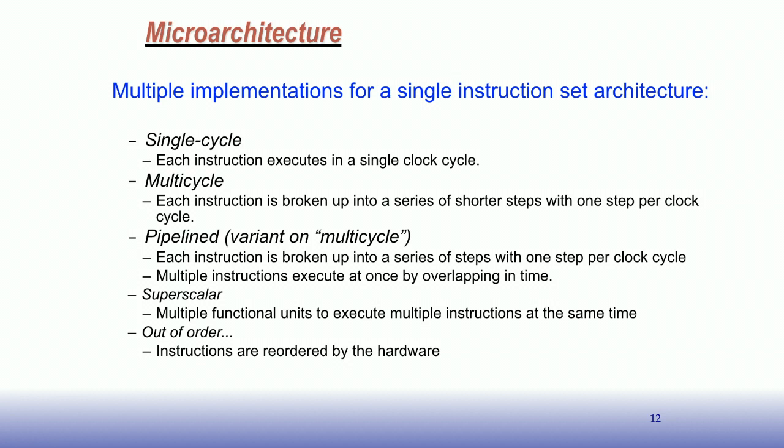We have a way to do it in a single cycle. What this means is each instruction executes in a single clock cycle. Nobody actually builds real processors this way. We teach it this way. We're going to do that today because it's a really nice and simple way to understand how to do processor design. Once we do a single cycle processor design where every instruction executes in exactly one clock cycle, then we can show how to make it a higher performance processor by pipelining it.